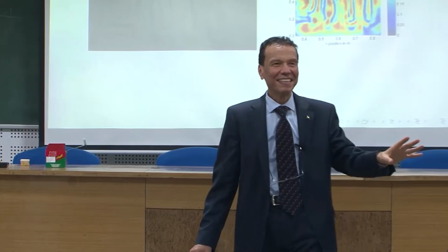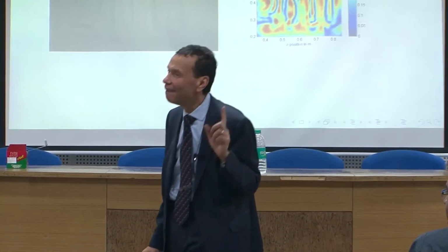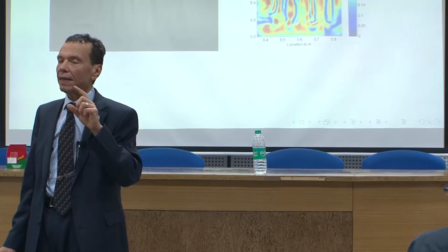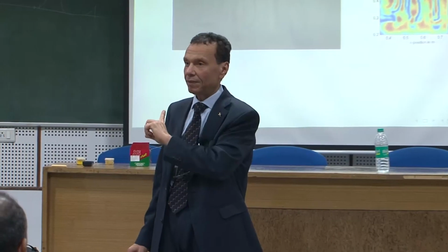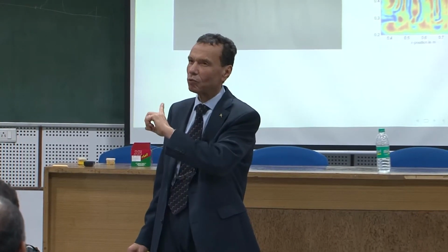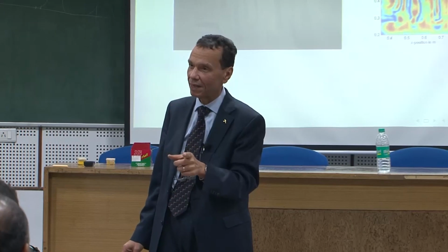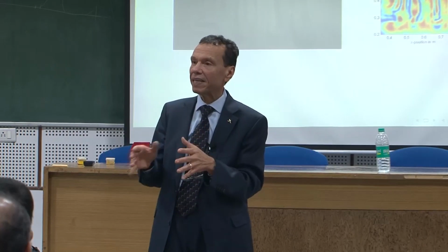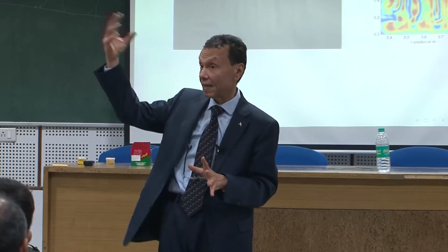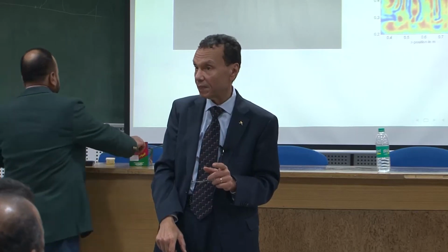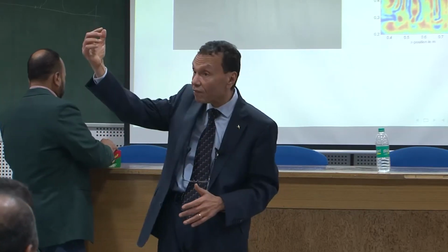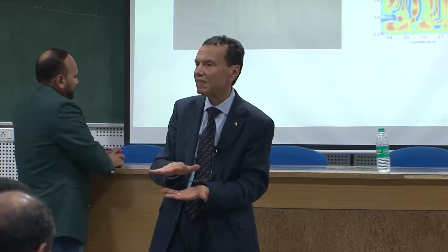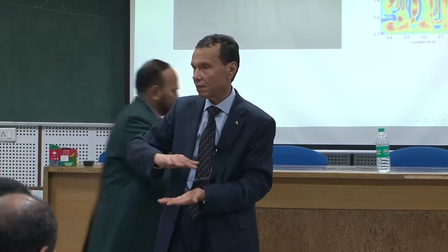So any other question? Why have we used different bands, X, Ku, K? Because this is regarding penetrability, which I told you before. Still, remember, as we talked about the Rohde & Schwarz network analyzer, it has very, very low frequency. I know from the very beginning that the resolution is not as good as at 40, but I can penetrate deeper at 6 gigahertz. But at 40 gigahertz, I have better resolution, but I may detect objects maybe 10 to 15 centimeters below the floor.